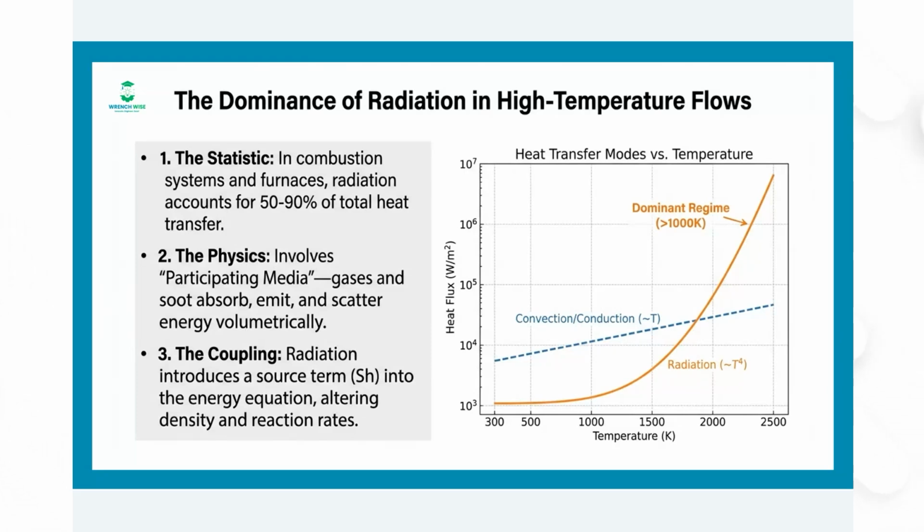Previously, we spoke about solid surfaces radiating heat, but now we are talking about participating media. In high temperature flows, the air itself is not clear, because it is full of soot, smoke, and combustion gases, so to speak. These particles absorb and emit energy sort of volumetrically. This means the fluid isn't just carrying heat via convection, but the fluid itself is also glowing via radiation.